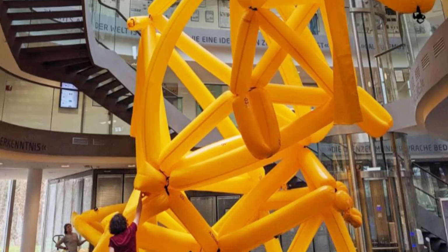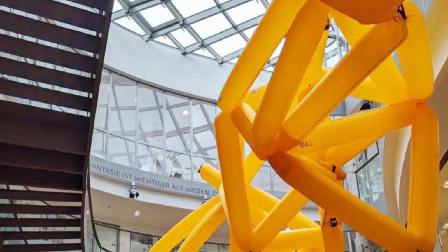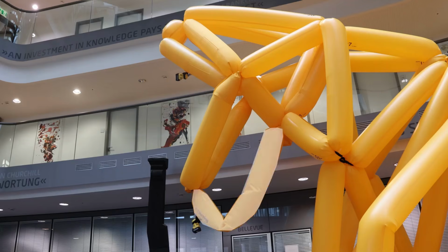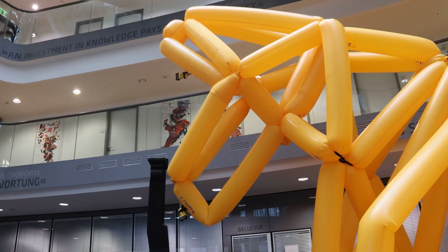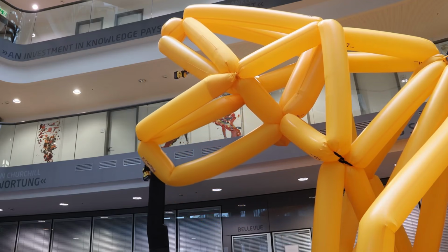The dinosaur model, shown earlier, offers 3 degrees of freedom. Each of them has slightly different requirements. The dinosaur's jaws perform large movements and need to move at a reasonable speed. We achieve this by creating a variation of O'Neill's buckling actuator, the 2 ends of which we integrate into the single tube.